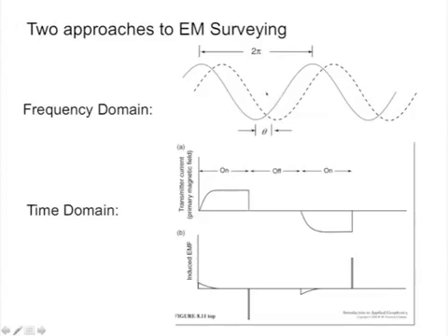Okay, so the receiver coil will see exactly the same transmitted magnetic field. So the receiver coil will see that, but it will also see something else. It'll see an induced magnetic field, which will be delayed by a whole lot more than nanoseconds. Okay, and in fact, we'll be able to tell that it's delayed by a certain phase, a certain percentage of the 360 degrees angle rotating around the circle from peak to peak.